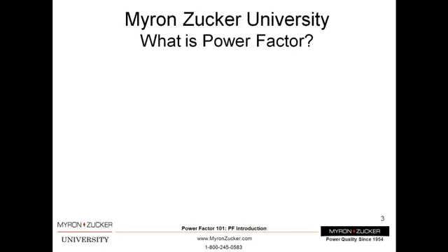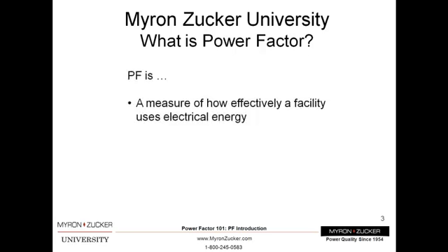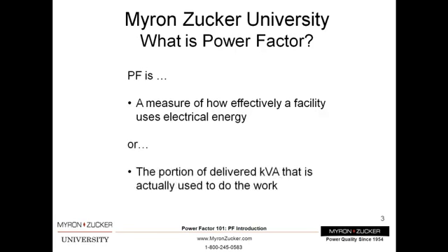What is power factor? Power factor is a measure of how effectively a facility uses electrical energy or power. Since electrical power is provided as volt amperes, or more commonly kilovolt amperes, kVA, power factor is defined as the portion of delivered kVA that is actually used to do the work. Power factor is not to be confused with efficiency.